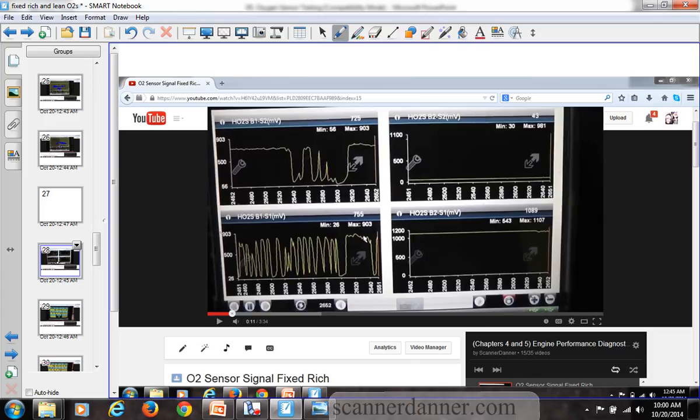He did an RPM drop test on the passenger side, unplugged injectors or the ignition, I can't remember. And there were no RPM changes on one half of the engine. He thought it was something mechanical, but it was intermittent. Turns out it's a dead O2. Look, bank 2 sensor 1.